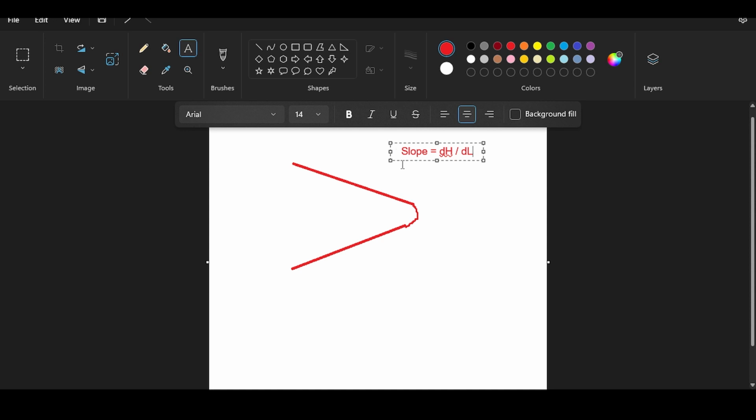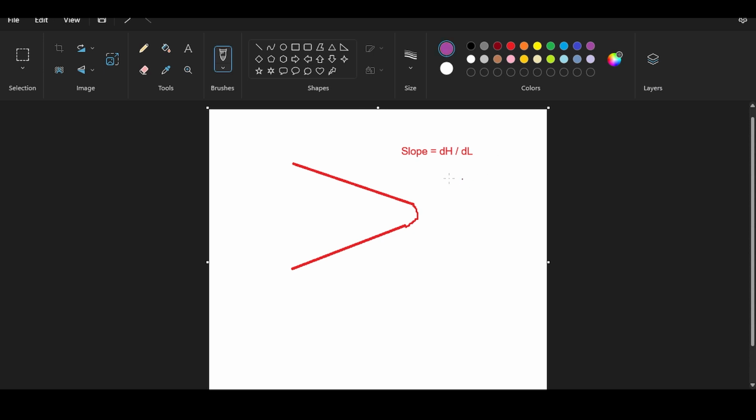And the length here is the length that contributes to you going down. And since the helix here is spiraling down, the length is actually the length of the ramp, the length of the spiral, and the length of the other ramp. This means that the slope for a spiraling curve is actually lesser and milder and better for cars, because your length will include the helix or the spiral here because it's going down.